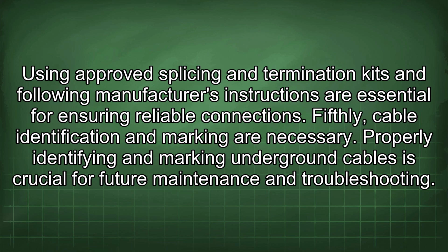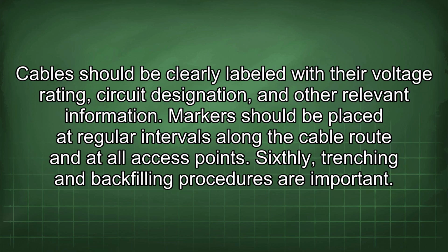Fifthly, cable identification and marking are necessary. Properly identifying and marking underground cables is crucial for future maintenance and troubleshooting. Cables should be clearly labeled with their voltage rating, circuit designation, and other relevant information. Markers should be placed at regular intervals along the cable route and at all access points.